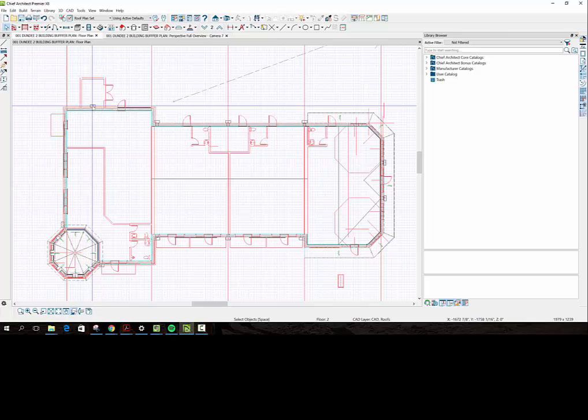Okay, let's figure this out. Right now, we've got a downspout that's going into the trash area. This downspout has to be here in the corner because it's going to be in the way of the awning. So we've got to get the water down into this corner. This was just done for symmetry. We can scoot that anywhere. I think for our purposes, what we really want to do is create the high point for the truss. Keep everything simple.